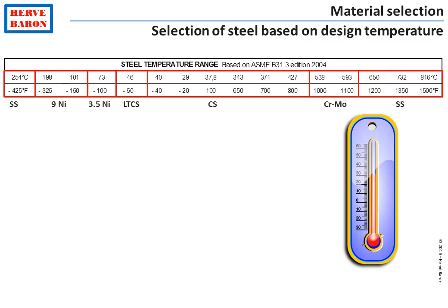This shows, for instance, the material selection as per the usual piping code, showing that stainless steel will go down to minus 254. And if one needs to go, for example, to a temperature of 800 degrees Celsius, one has to also use stainless steel.